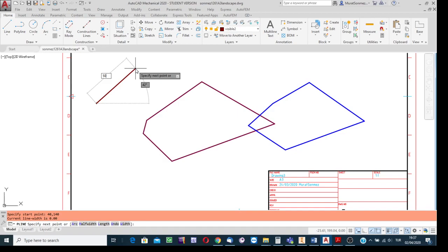Do not click on the tab key. Click on the comma key. Okay? But here it is important. I am saying delta x. To be able to teach the software that it is the delta x value, not x but delta x, the dynamic input button must be on. If the dynamic input button is on, then there is no need to use the at symbol.